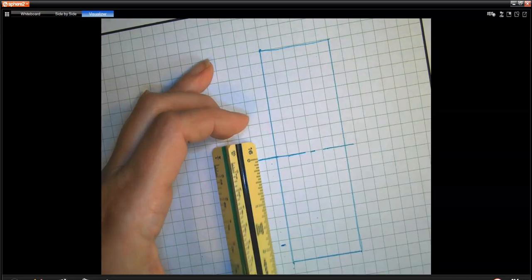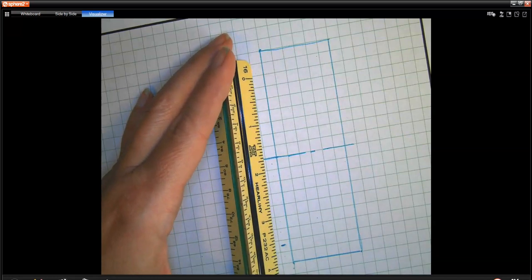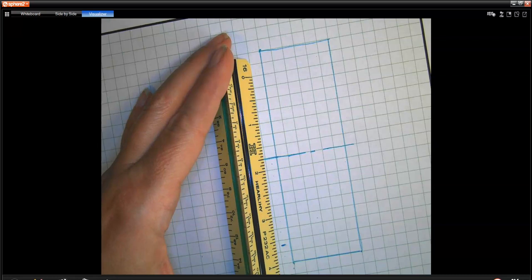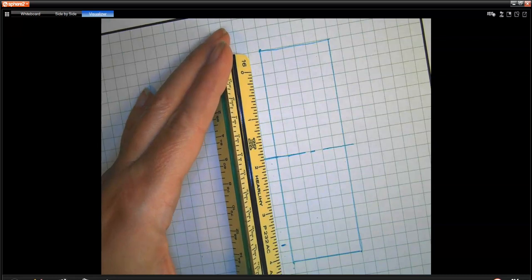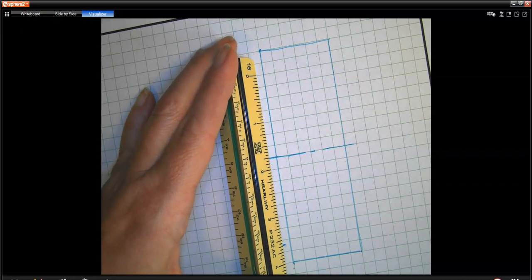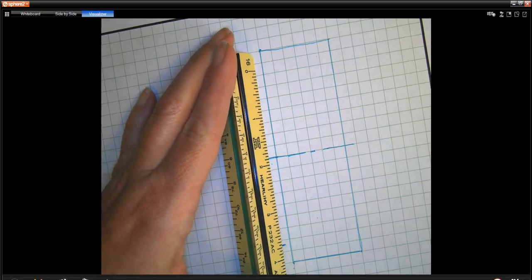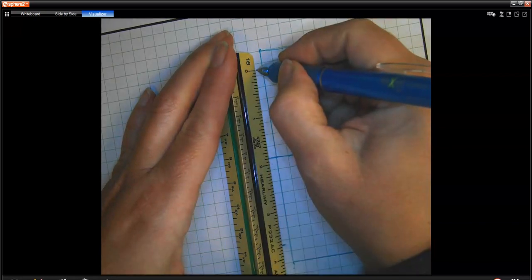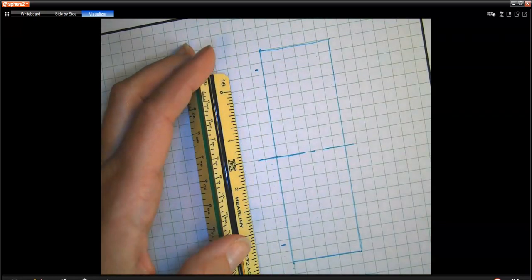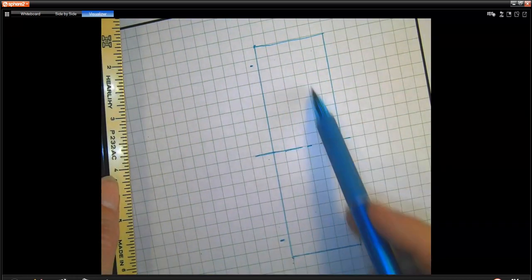So 7.5 blocks up. And on the other ones, the second one has the exact same dimensions, but just looks a little bit different, and the other one is 1 5/8. So either grab a ruler or know that half of one of those blocks is an eighth of an inch. So every block is 2/8. So it should line up in half of a block. So that is going to be the location for that inside cutout.